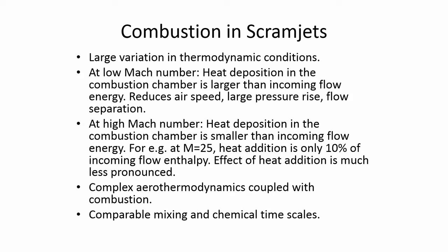Whereas in a scramjet, there is no such rotating machinery to control it, and it's only the cross section area that changes it. So any small change upstream or downstream, or in the flight parameters like the flow speed, can also lead to a large change in the combustor entry conditions, and the variation can be both in thermodynamics as well as in the flow parameters. Okay.